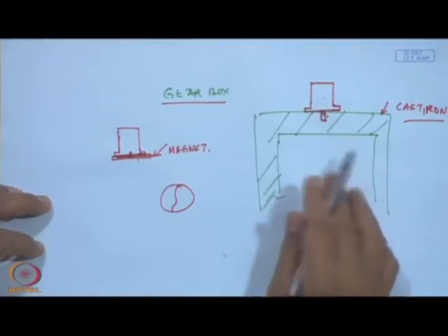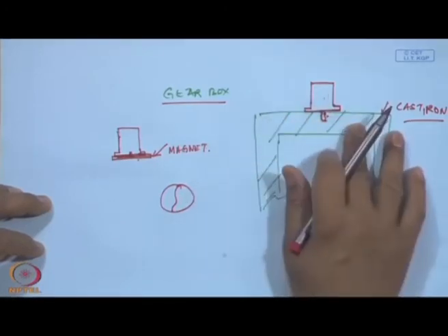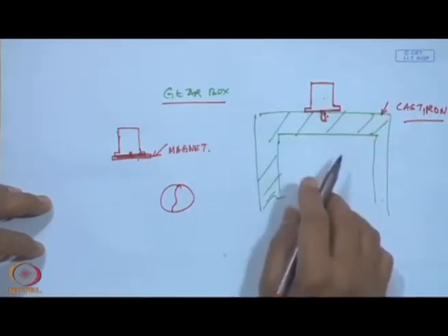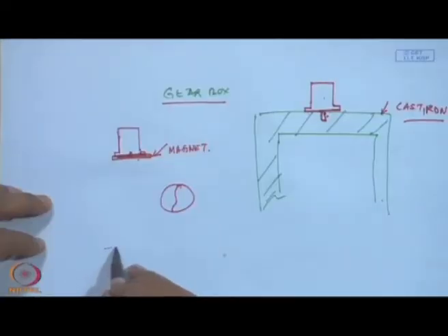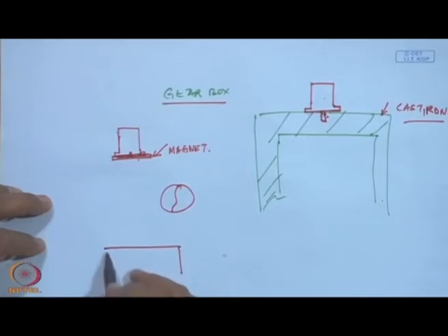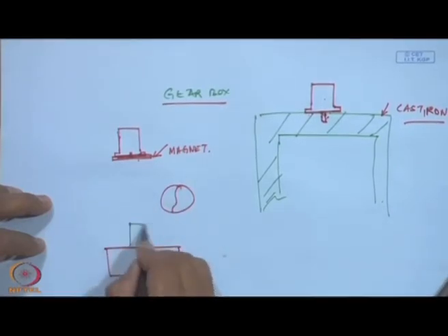Sometimes these surfaces are so hard, or the OEM of some machine would not allow you to do any tapping, which would permanently damage or weaken the structure. How do you do that? In such a case, what you do is glue a block onto the surface.